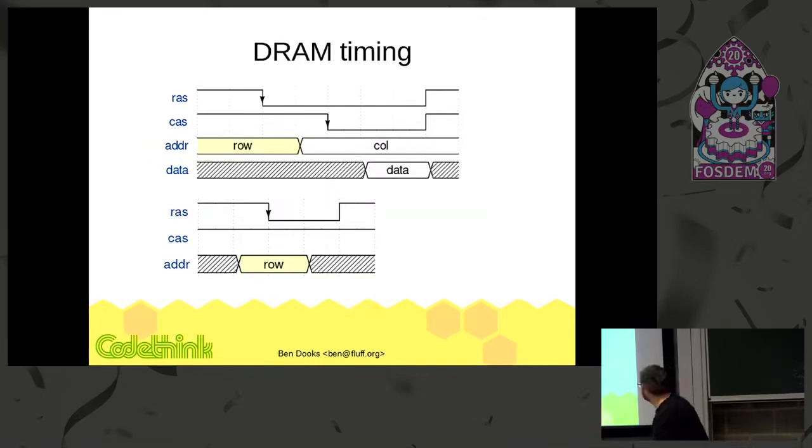And going with how the DRAM would work, you start with the row address of the row you want, and that's sampled roughly on the active edge of the RAS signal. The column address is again sampled on the active edge of the column address strobe, and then at some point pretty soon after, you either read or write the data.